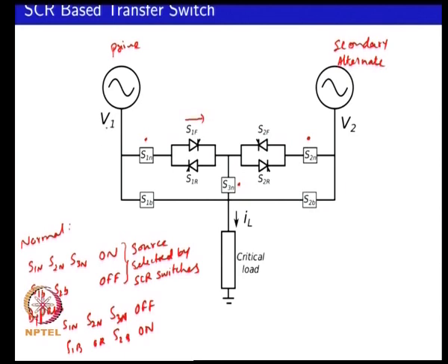It is a positive half cycle, S1F is conducting current, because the load is unity power factor. So, this voltage has gone down to 0, and now this voltage is also in phase, which means that this is also seeing a positive voltage. So, if you can turn on S2F, then you could reverse apply a negative bias to your thyristor S1F and be able to turn off the thyristor by making use of your alternate source. So, in this particular manner you could actually get faster transitions,